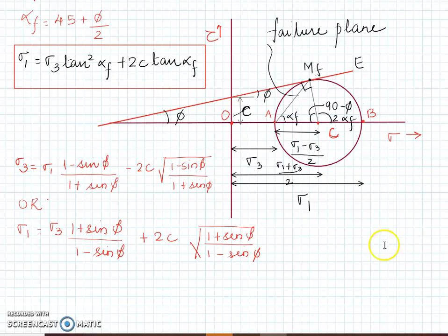Okay. In your 4th unit, I do not know whether you all have covered this, but there is something called coefficient of active earth pressure, coefficient of passive earth pressure. Probably you all might have used these coefficients when you have designed retaining walls. Now what is this coefficient of active earth pressure that the ma'am will teach you in the 4th unit? It's basically when you design a retaining wall, and a retaining wall moves towards the backfill.